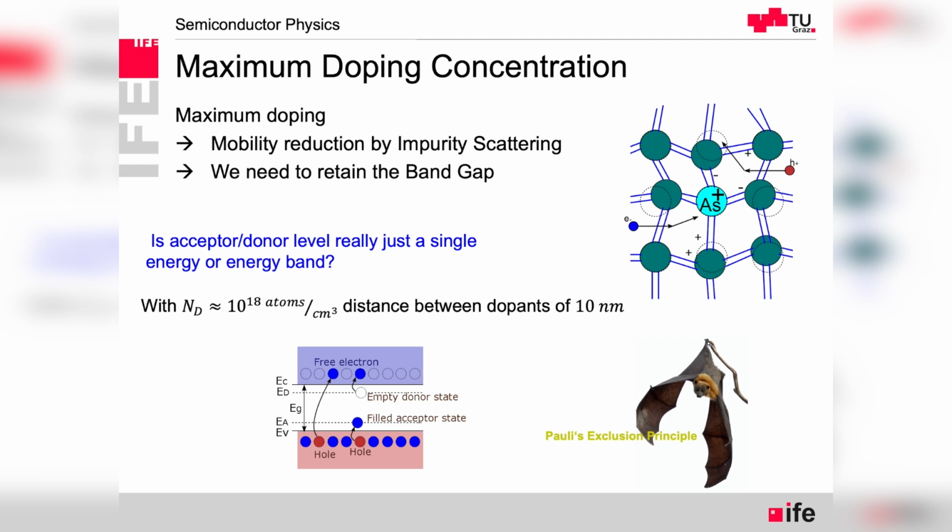And finally, at some point, when we place the dopant atoms in silicon, we have to activate them. That means with high temperature, we ensure that the covalent bonding between the atoms takes place. And at some point, we cannot find space in the crystal anymore for the dopant atoms, because there are just so many that they won't be, so to say, integrated in the silicon structure.